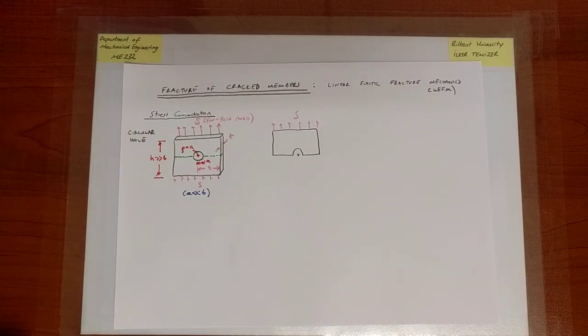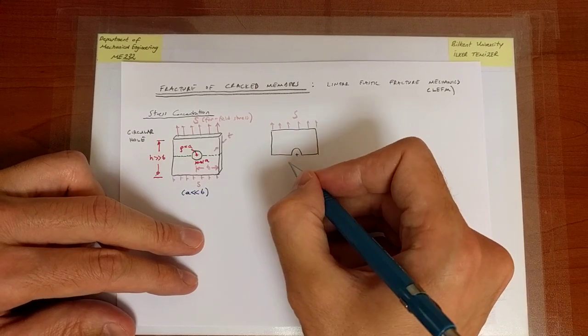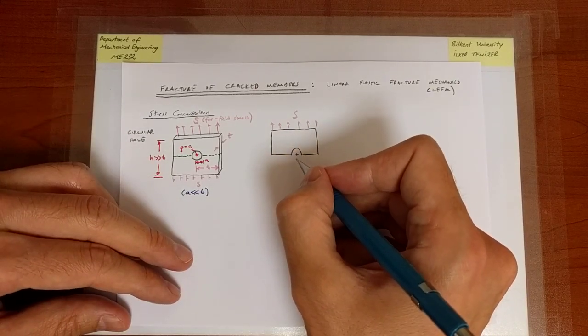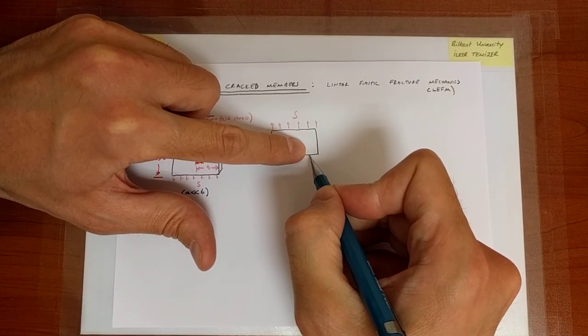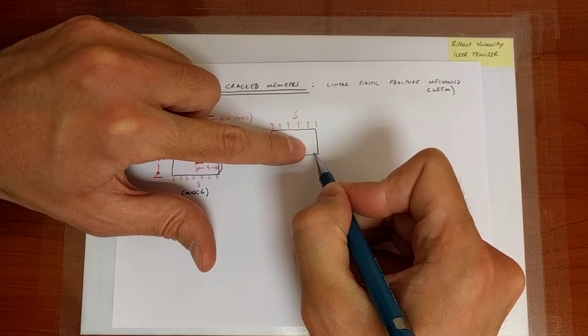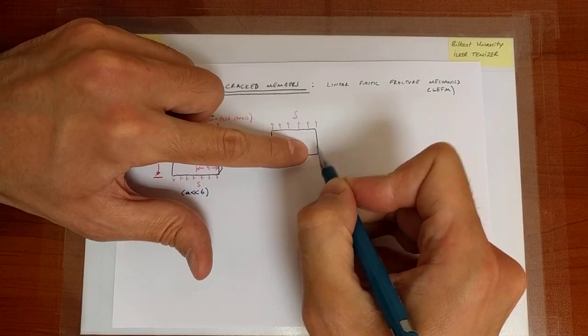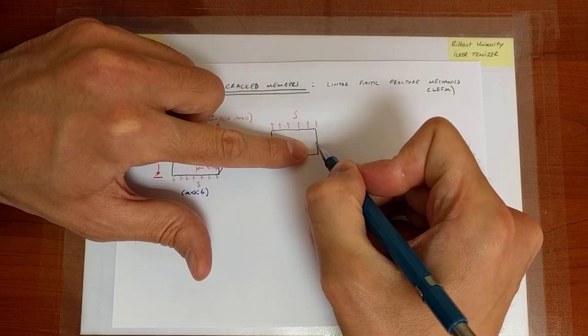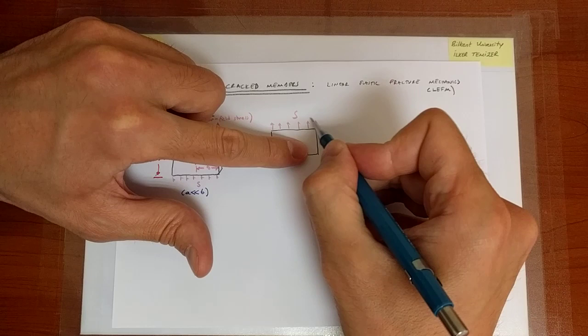Well, what we can remember from ME 231 discussions is the concept of a stress concentration. Now, the stress concentration idea works in the following manner. So we have a hole, assume that it is sufficiently small such that if I am sufficiently far away from the location of the hole, the points here do not really feel the presence of the hole, so they think that the normal stress is the same as the stress that you encounter in further upper portions of the plate, which is S.